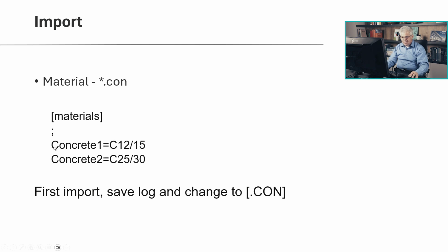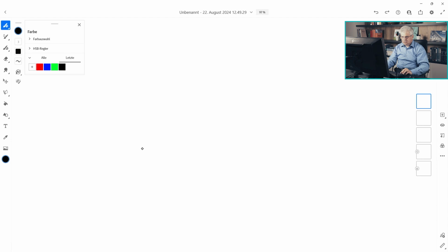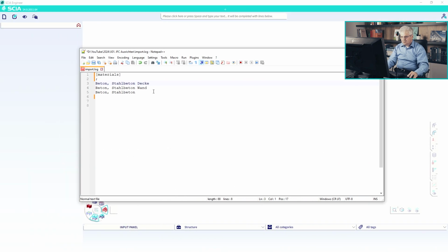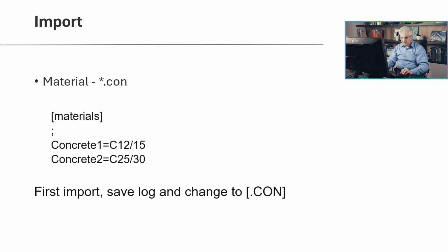And then we have the name in the IFC file is equal to a name in SCIAEngineer. So, sorry. So I will write this name is equal C2025. If you have a blank in SCIAEngineer in the name of the material, you have to write it correctly. So everything have to be written. So I will copy it here and here. So should we have some blank between them?